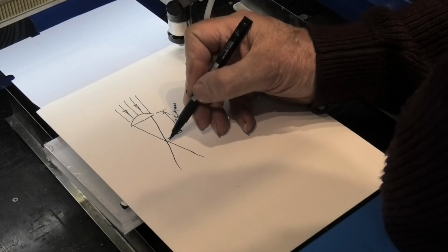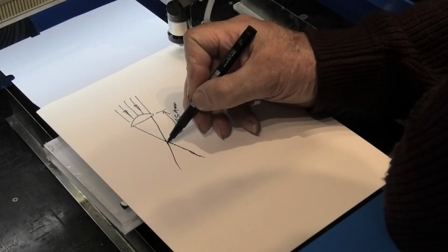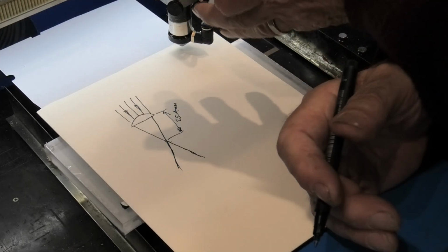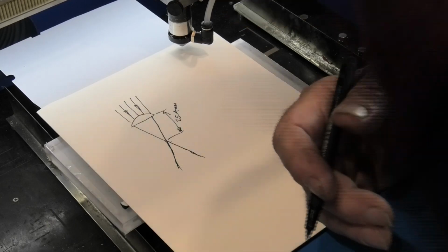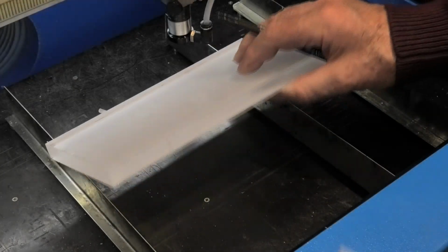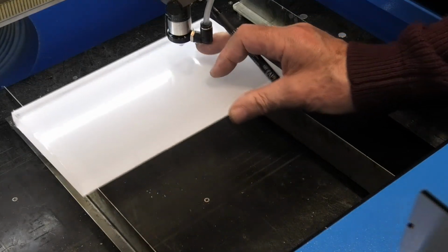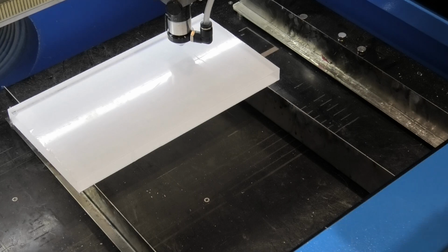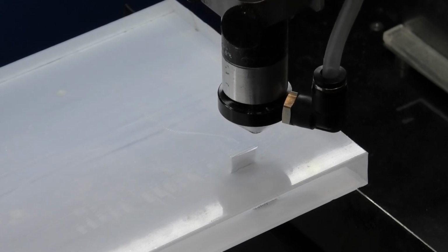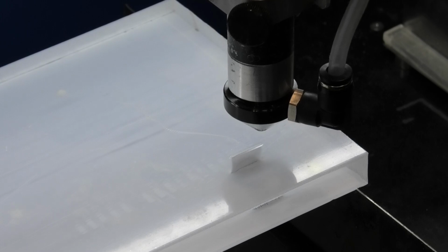After the focal point, this lens expands very, very quickly. I've got 70 watts on this machine. I should not, according to general principles, be able to cut a piece of 15mm acrylic with such a short focal length lens and relatively little power. People would tell me that I need probably 120, 150 watts and a 4-inch lens to cut this stuff. It's going very, very slowly, 1mm a second. But I am trying to do the impossible here.